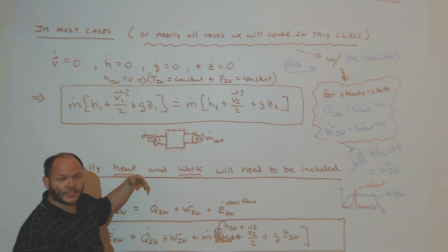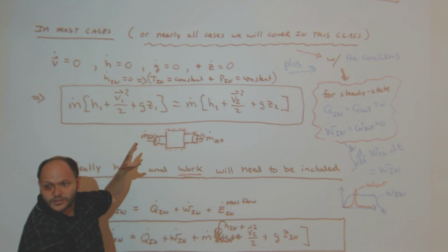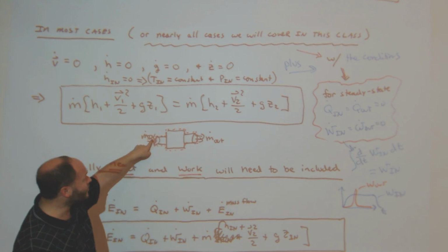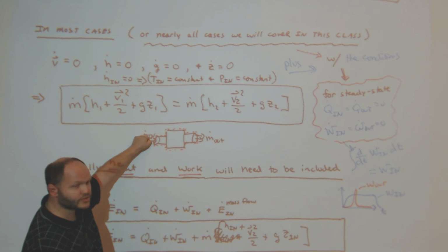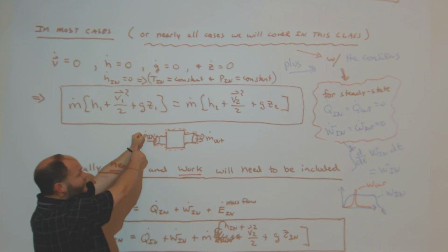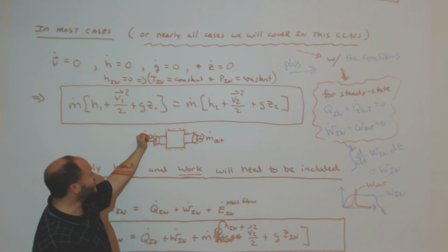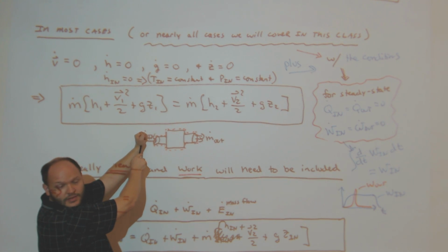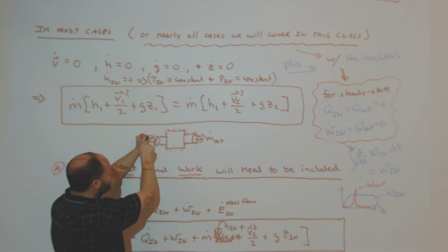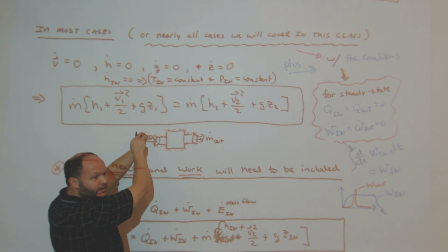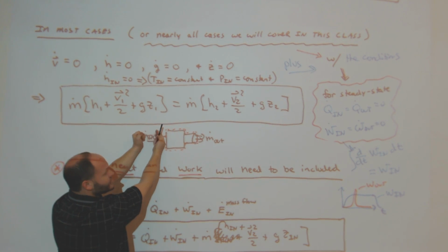And I have mass and heat coming in, and mass and heat leaving. The system can also do work, so you can have energy transfer. But for mass coming in, there's a control volume of what's coming in, right? So this defines the control volume of air coming into my system. It's traveling at a velocity. There's a given density, there's a given temperature. And then, of course, there's a control surface and a boundary associated with my control volume of mass coming in, but it comes into my system which crosses some boundary.